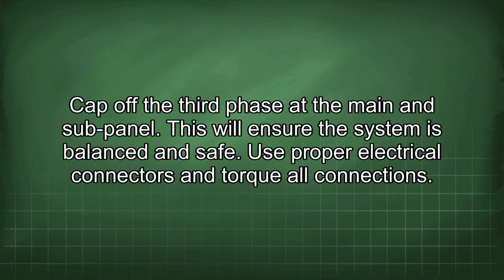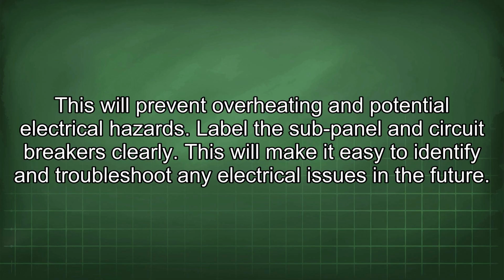Use proper electrical connectors and torque all connections. This will prevent overheating and potential electrical hazards. Label the subpanel and circuit breakers clearly. This will make it easy to identify and troubleshoot any electrical issues in the future.